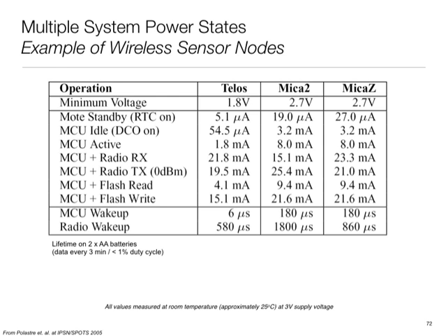These are not the ones like, oh, it's 1 milliwatt when it is computing. In fact, oftentimes that's a smaller contribution to overall lifetime energy. If I have a system like my heart rate sensor example, it's sending a tiny packet every second, let's say. It probably takes a few milliseconds to measure the heart rate. A packet at typical speeds that Bluetooth offers takes a few milliseconds. So every second, I'm probably running maybe 10 milliseconds, maybe 50 milliseconds. The rest of the time, I can be asleep, doing nothing. So the energy taken during that time is more important than the energy consumed while you are actually doing the work, because when you look at the lifetime integral, it's going to be that idle time which dominates, and many applications are like that.